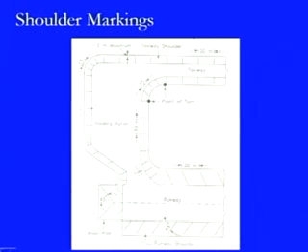That is the part of the runway, and as soon as it comes to the holding apron, then they become perpendicular to the edge. So, we can look at these perpendicular strips being provided, and at the maximum they can go up to a distance of 1.5 meters like this. And here this is the point of turn, and in between these points of turn it is located at a distance of 15 meters. So, this is how they are being located here. From the edge it is 1.5 meters from this side.